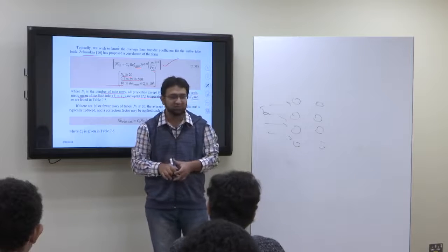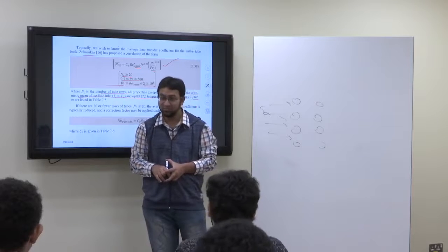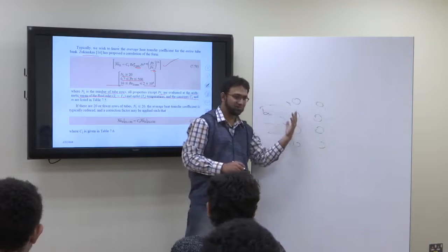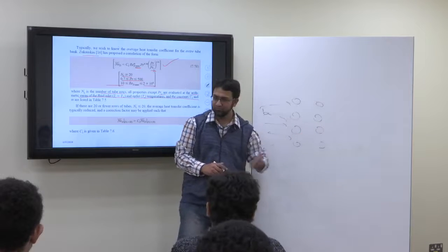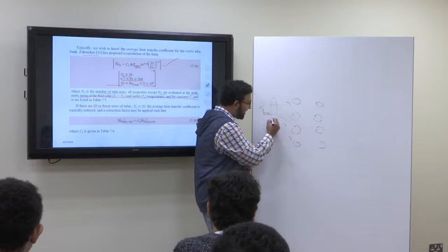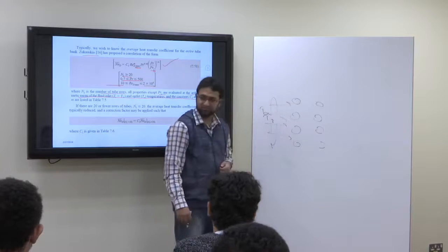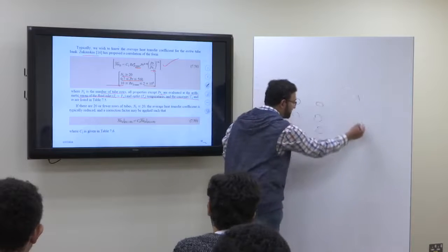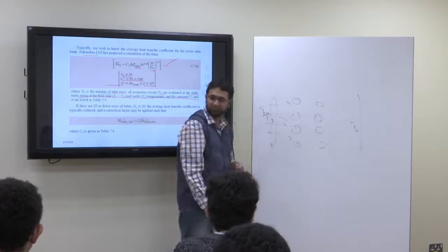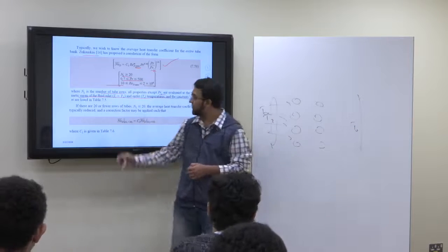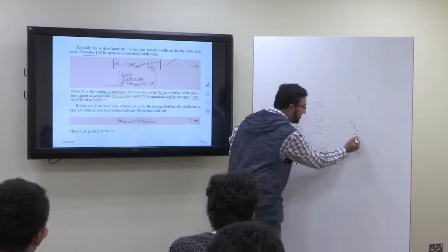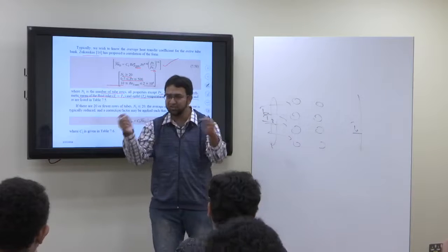But do you think that the free stream temperature would remain the same? No, it will change, because the heat is being transferred to or from. So we will have a mean of these temperatures, say Ti at the inlet, and a mean of these temperatures once it passes through these banks of tubes, so T out. These properties are not found at Ti, neither at To, but at an average of Ti and To.